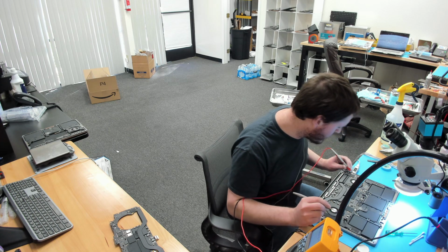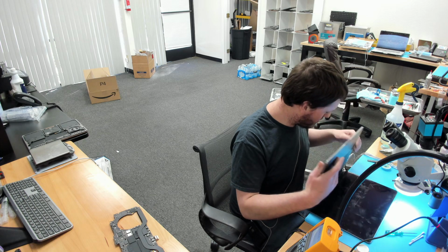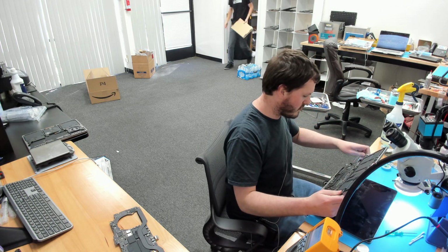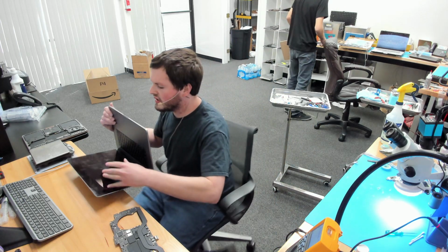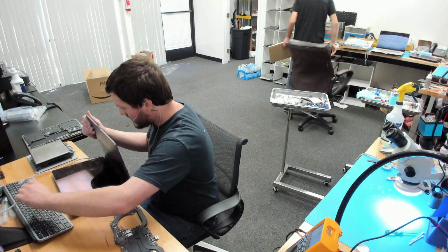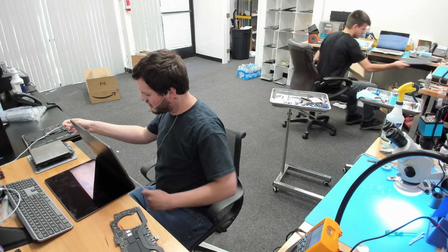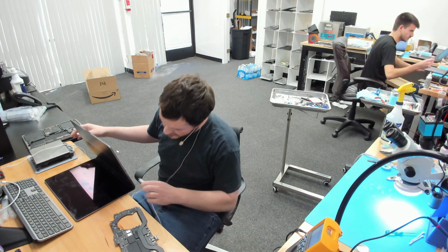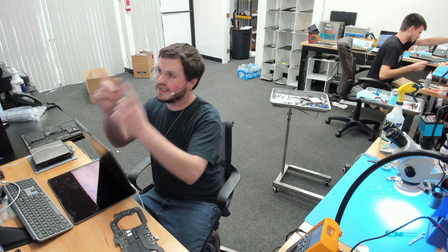I don't see anything at this point electrically wrong, other than the fact it's not booting. So this makes me think something happened when that capacitor shorted. What did that capacitor cause? So this makes me think it's in recovery or DFU or something like that. So we do have battery voltage. I'm going to go ahead and plug it into my machine right here and see if this is possibly in recovery or DFU mode, which can happen quite frequently when you have issues like this sometimes. And it is in recovery mode.